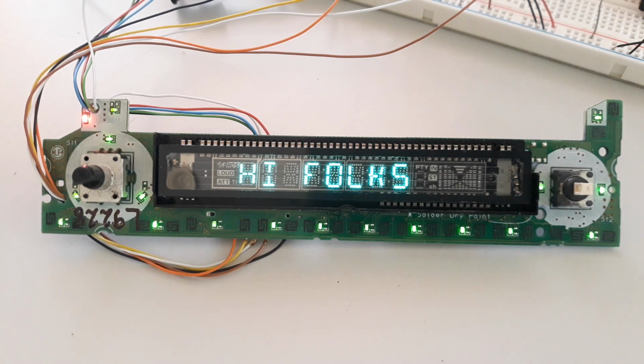The driver features a 5x6 key matrix and has a push button and a quadrature knob as input modes. What I like about this driver is the fact that it works with a voltage between 8 and 18.5 volts positive in relation to the GND to polarize the grid and segments.